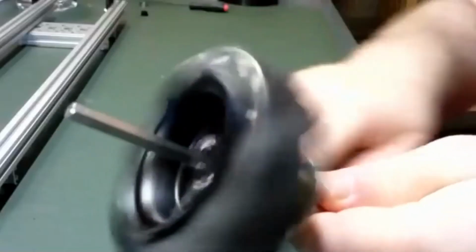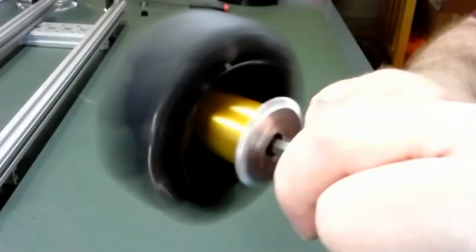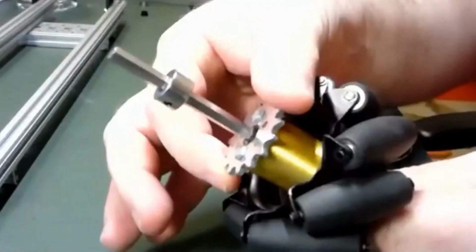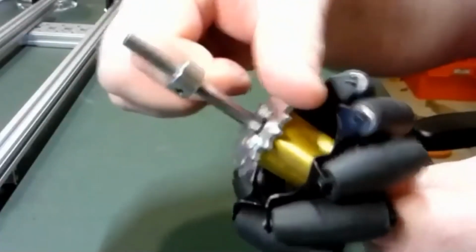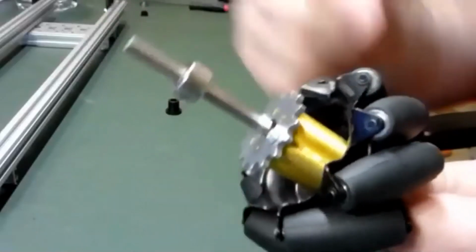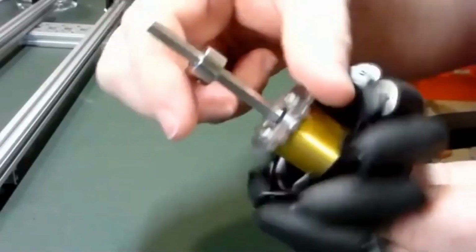So dead axle means that I can get the wheel spinning around the axle itself. The way the motors will then drive the wheel is by a sprocket and chain. The motors will have a chain, and they'll be able to turn the sprocket. Since the sprocket is attached directly to the wheel, when the sprocket turns, the wheel will turn with it.